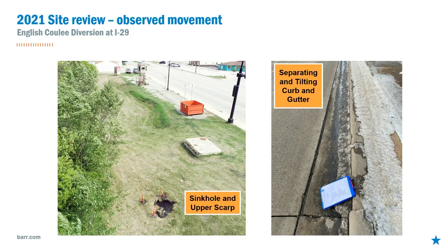Additionally, on the right, it's maybe a little hard to see, but our curb and gutter has started to drop significantly. We've lost drainage in that area. It's starting to pull apart from the driving lane pretty significantly. The sidewalk has dropped. We have some street lights starting to tip. And we know that scarp goes into that driving lane a decent amount. That driving lane is more significant concrete that's withstanding some of that slide movement at the time. But we want to start looking at mitigating this before we see something move into the driving lane that is going to cause a little more concern.